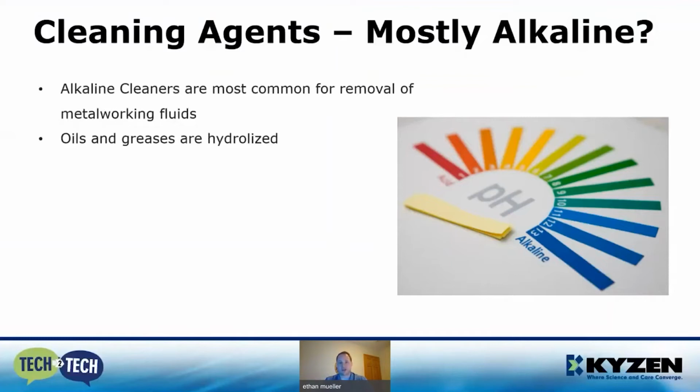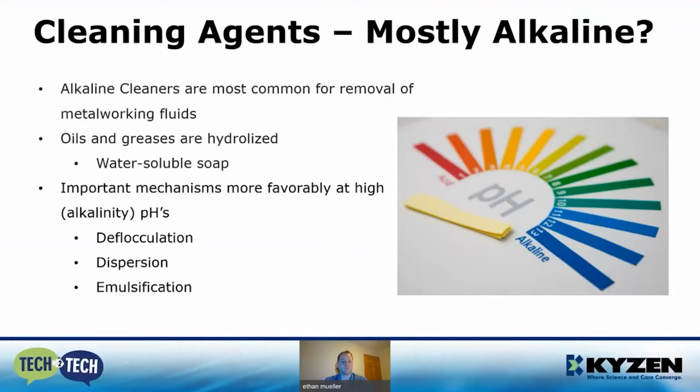Oils and greases are actually hydrolyzed by alkaline products, which forms a water-soluble salt, allowing us to easily rinse the oil or grease away from the surface of the part. Another reason that most cleaning agents are alkaline is because a lot of the mechanisms that we rely on to clean our parts are more favorably carried out at a higher pH, things like deflocculation, dispersion, emulsification. And finally, some of the additives that we're relying on to clean our parts are not soluble at lower pHs, so we need to add those to an alkaline environment to get them into solution.